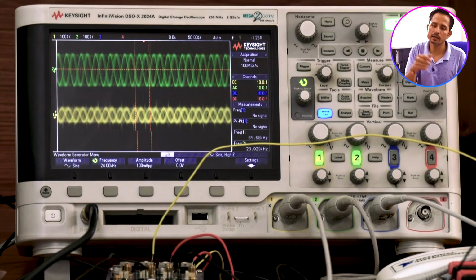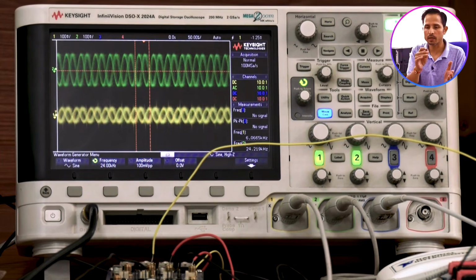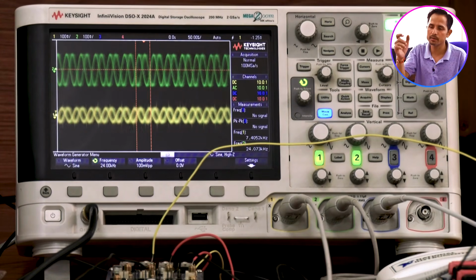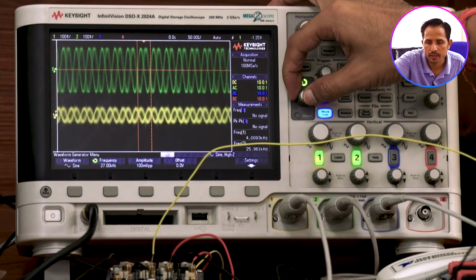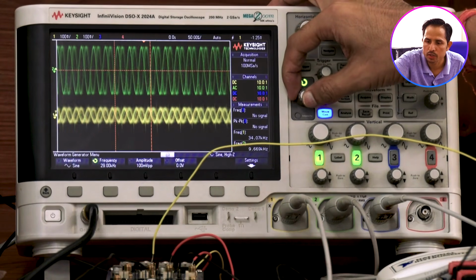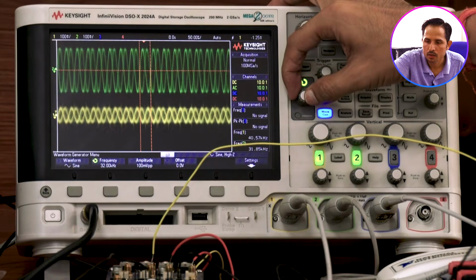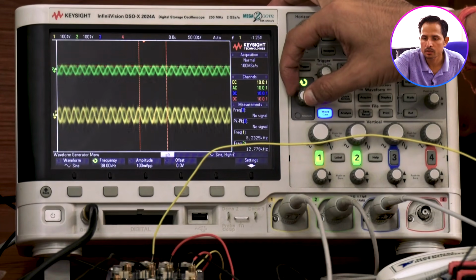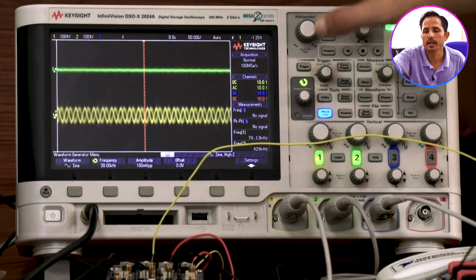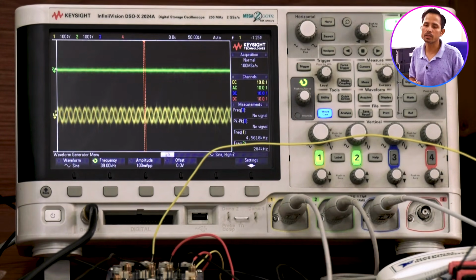So we can see that when we again go around 40 kilohertz, which is a multiple of 19.53, so it will be around 38 point something. If we go around that one, again it will start attenuating, and it will bring the output to 0. So I am increasing the frequency, 36, 38. We can see as soon as I go around 38 point, it again attenuates the overall signal.